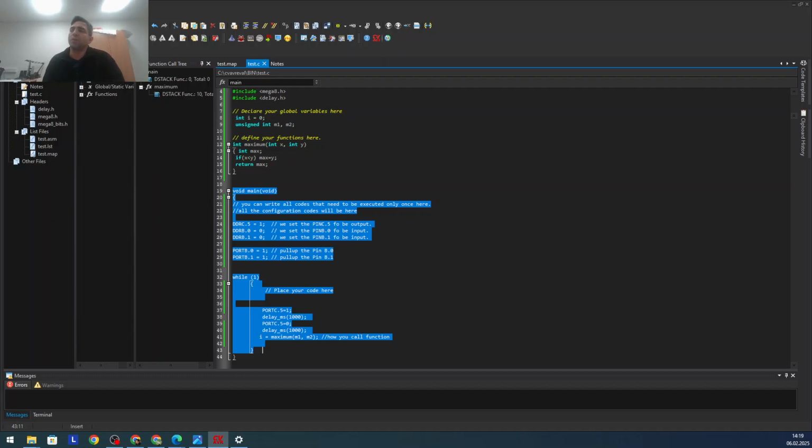And so far all of this was declaration and definition of the function. Main function is the code that the CPU will start executing line by line. If there is not this loop here, for example, while 1, this will go through all of this in literally a millisecond, not microsecond.